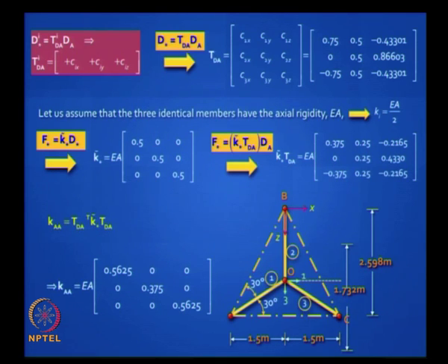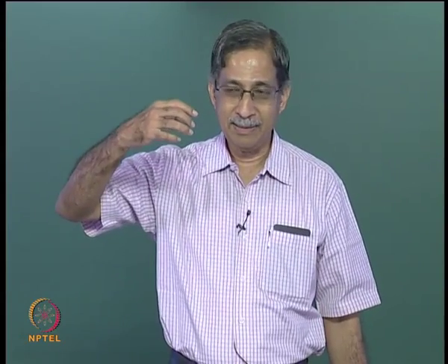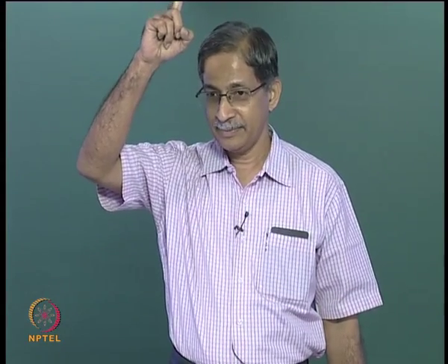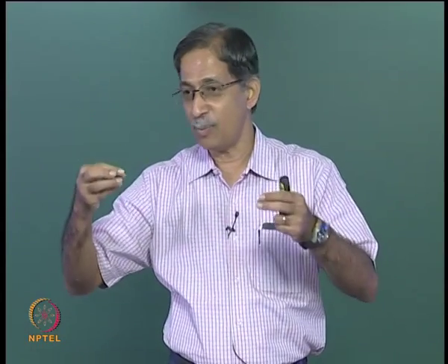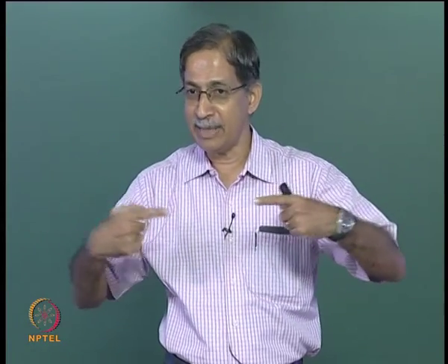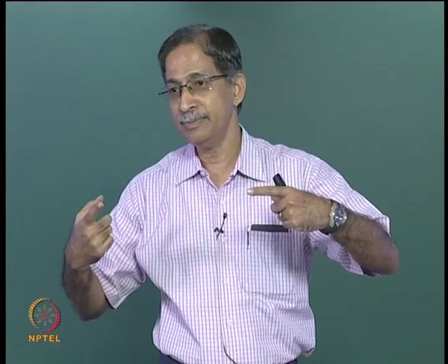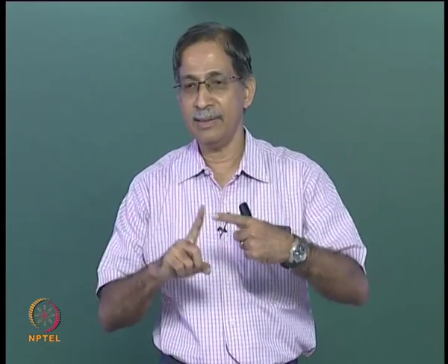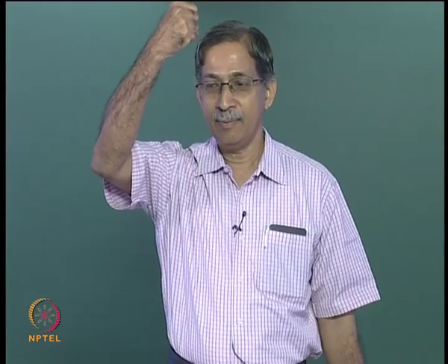Well, first thing, you have this tripod, if 2 is acting upward, it is symmetric. So if I arrest 1 and 3 and pull up 2, do you think where I have arrested there will be some reactions, because they will be K12 and K32, or there is no need to arrest, those points are not going to move. What do you feel? It is symmetric. When I pull something up, will it have any displacement in the horizontal plane? No. So it makes sense. So you have proved intuitively that K12 and K32 will be 0.